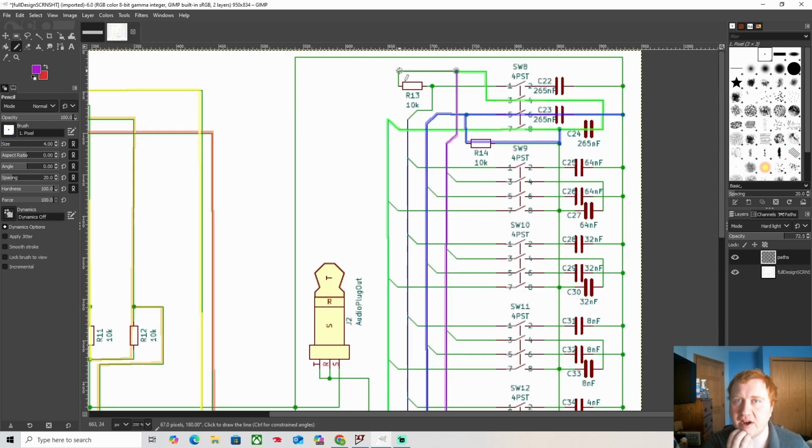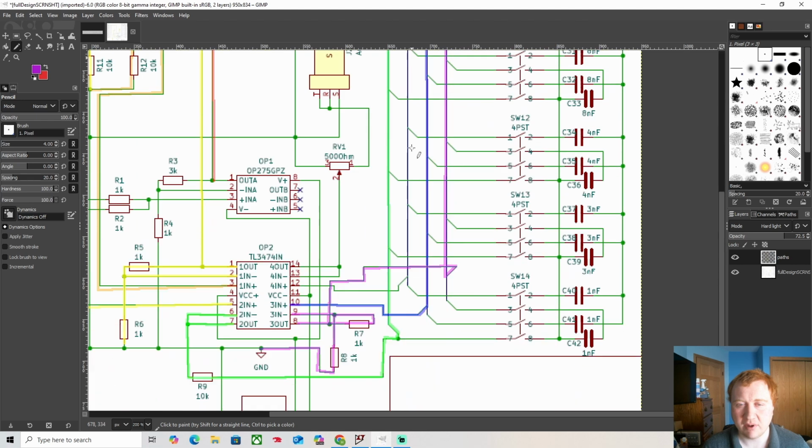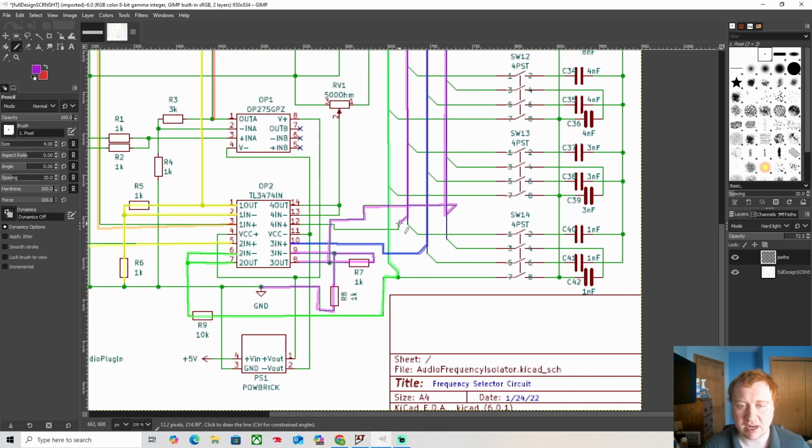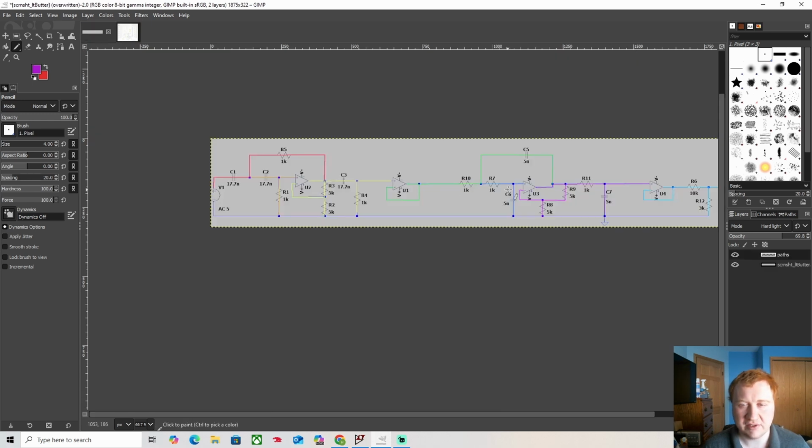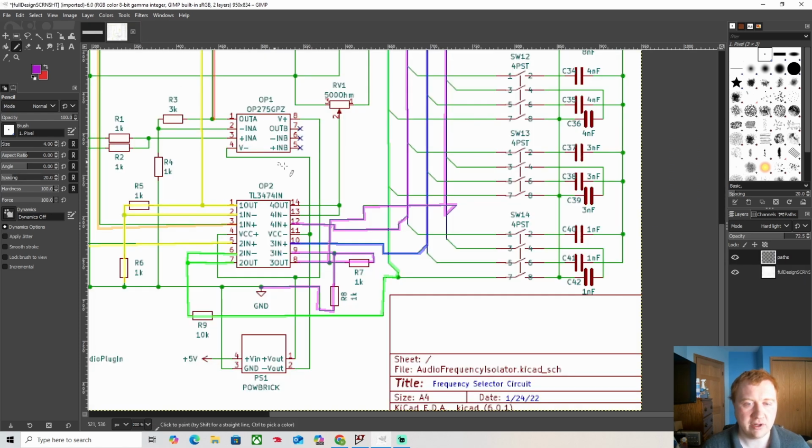And then we need the final stage, the last filter. So another R comes to this capacitor, which goes to ground, and then it branches off through the bus, down, up to the unity gain buffer, which is what we see here. So this is that line. And then finally we have the cyan color for the actual output, which is right here.